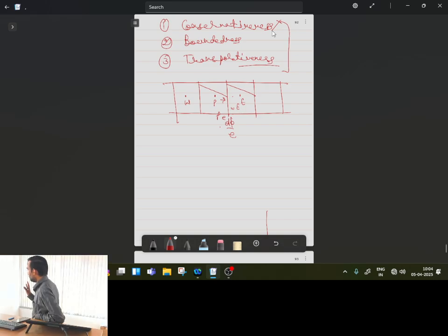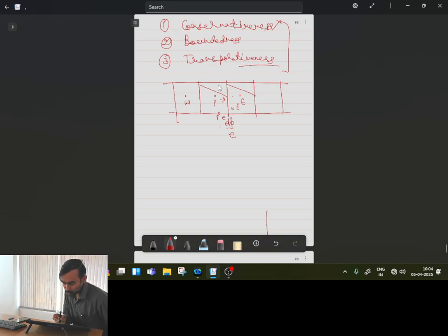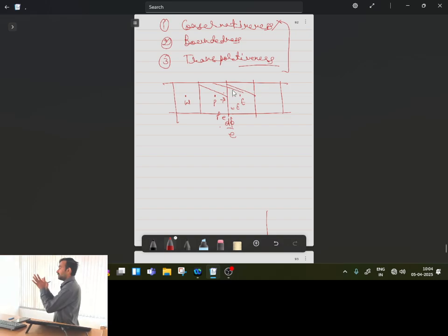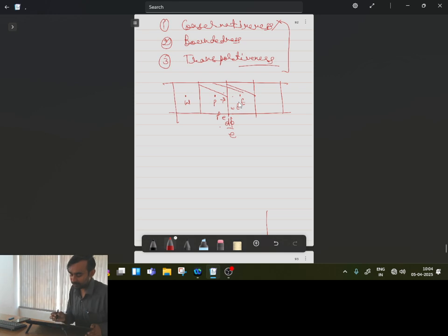All are clear with this point? So ultimately we have to choose the interpolation function in this way so that whatever is the flux leaving from this edge, the same should be the value of flux entering the other point. Otherwise, because of the flux discontinuity, there will be some error. So the scheme which does not satisfy this type of behavior is not conservative.